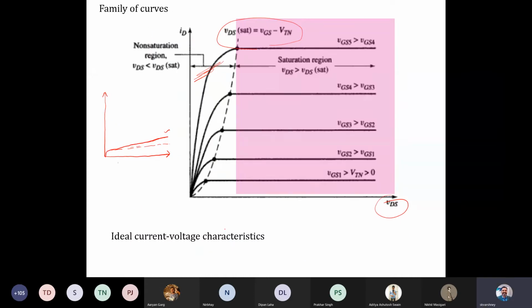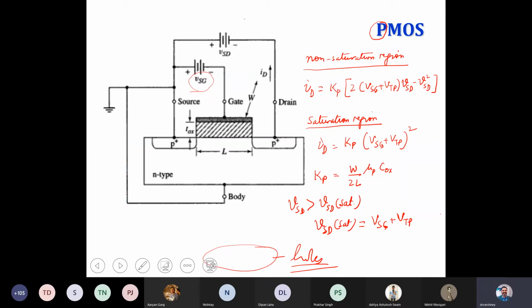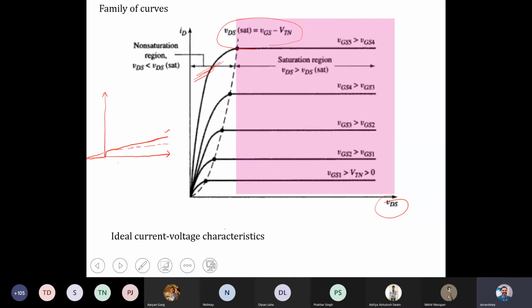Right, so we can write this in the same way we did for the early voltage in case of the BJT. If we extrapolate this curve onto this side, it will meet the x-axis somewhere negative, at some voltage minus VA, so we can define it.